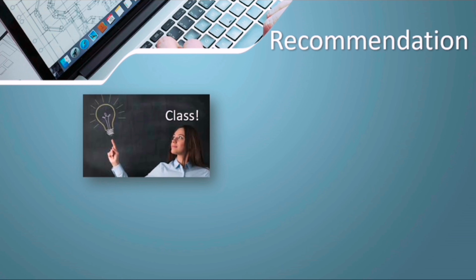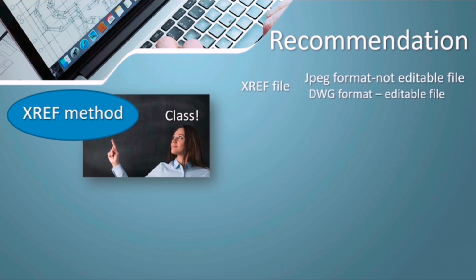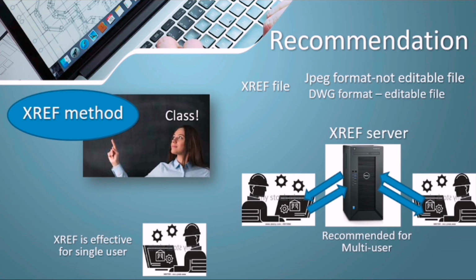Now, the recommendation is that we need to use this Xref method in teaching AutoCAD for our class. We can use an Xref file in JPEG format, a non-editable file, which I used in this research study. But we can also use the drawing format, which is an editable file. So the Xref method is effective for a single user as well as for multi-user. It is recommended for multi-user by the use of an Xref server.